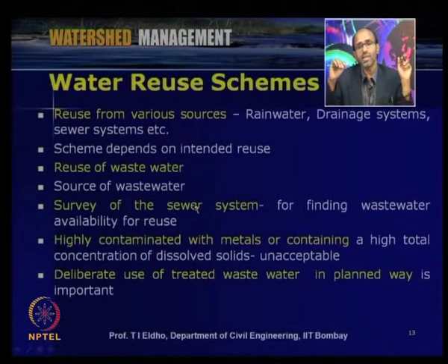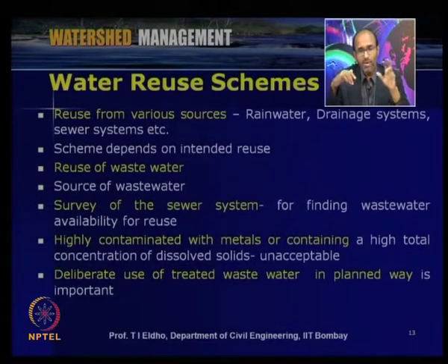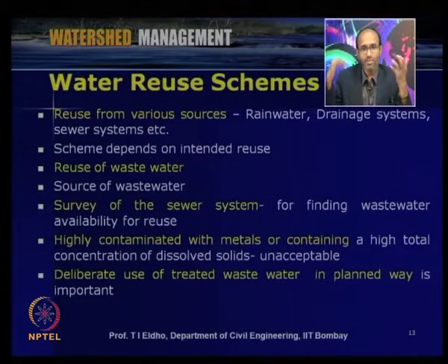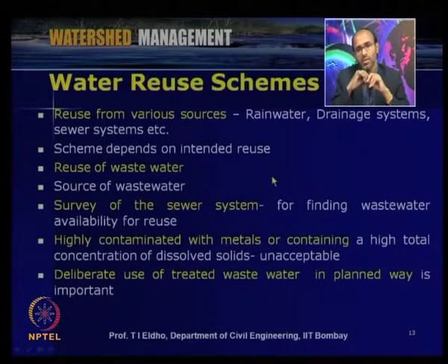When we look into wastewater reclamation and reuse, in a particular area we have to study the system and the quality of the wastewater coming. We have to collect samples from the various sewer systems and then identify the parameters within that wastewater before going for the appropriate treatment to be given. Highly contaminated wastewater with metals or containing a high total concentration of dissolved solids is generally unacceptable for most uses, especially where domestic or industrial purposes are concerned.